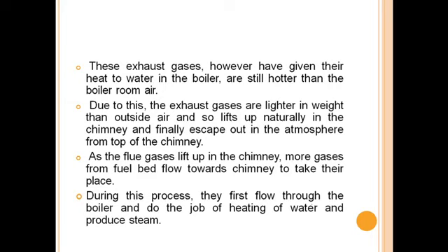As the flue gases lift up in the chimney, more gases from the fuel bed flow towards the chimney, and during this process they first flow through the boiler and do the job of heating water and produce steam.